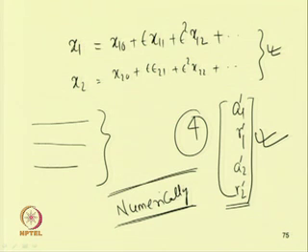To solve these equations numerically, one may use Newton's method to find the solution of the system. Unlike in case of a single degree of freedom system where we get a maximum of 3 branches, in this case we may get multiple solutions or multiple branch solutions.